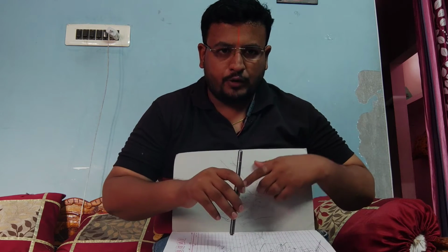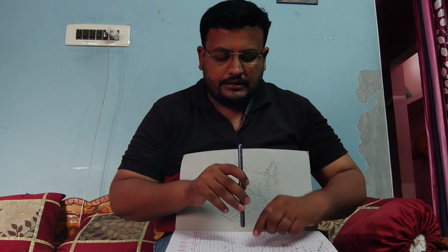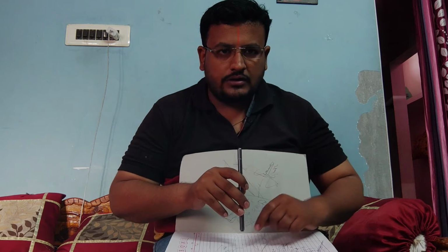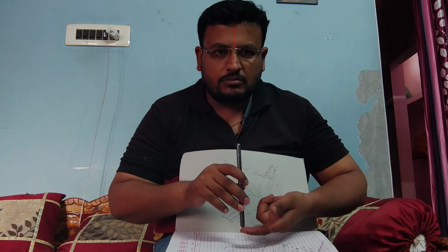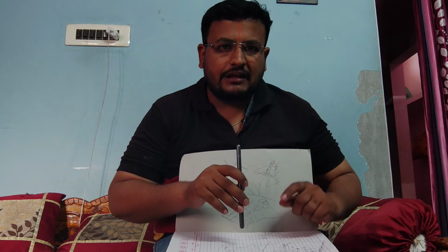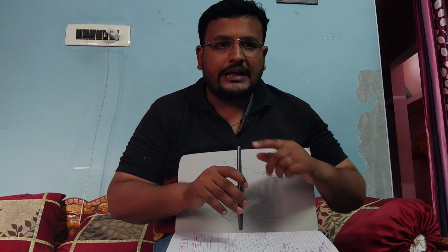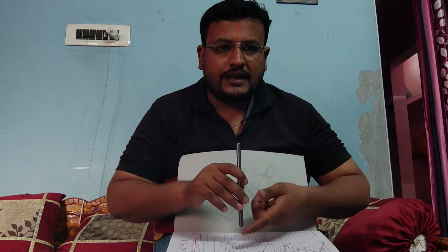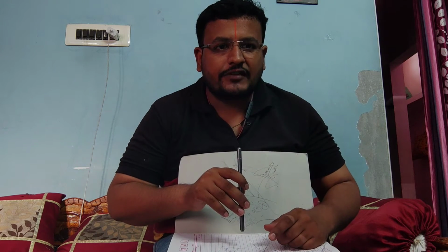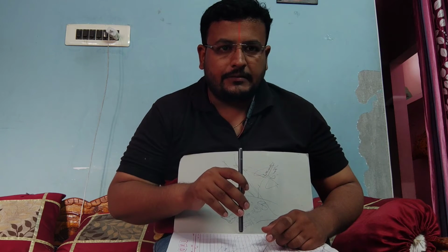And from the top view, if you put some light from the top, you can see this line in the form of a point on the horizontal plane. The topmost point can be seen, but the bottommost point cannot be seen. Therefore, the topmost point is represented with the same letter, and the bottom point in brackets. That means for AB, we represent it as A, with B in brackets.